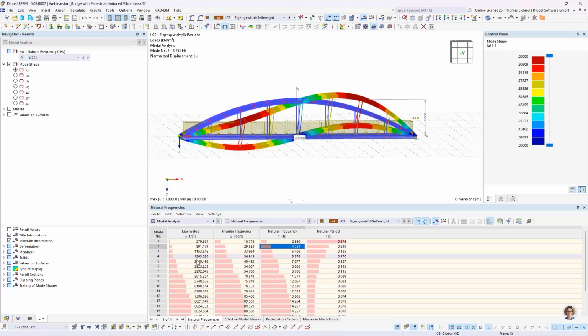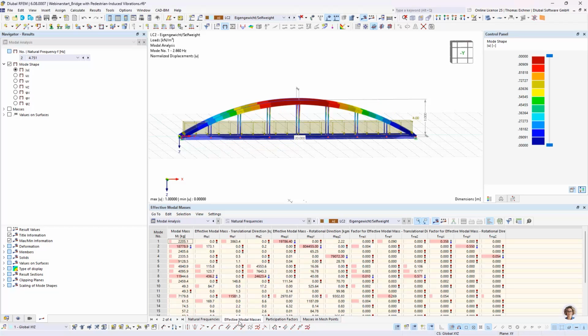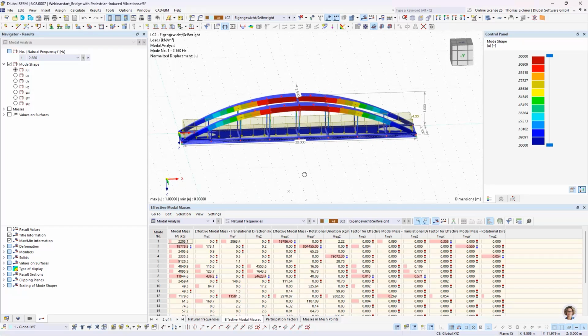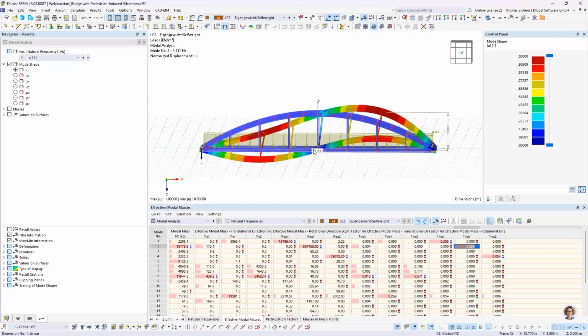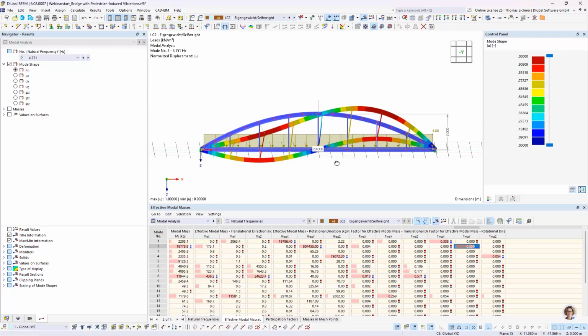So let's also look into some tips on how to find relevant frequencies. Maybe you know it from the seismic webinar already. We have also those effective masses available here. And we see now our second one has about 55% about the y-axis, which is quite right. And with that, we know this loading is of importance. So around the y-axis is important for us.